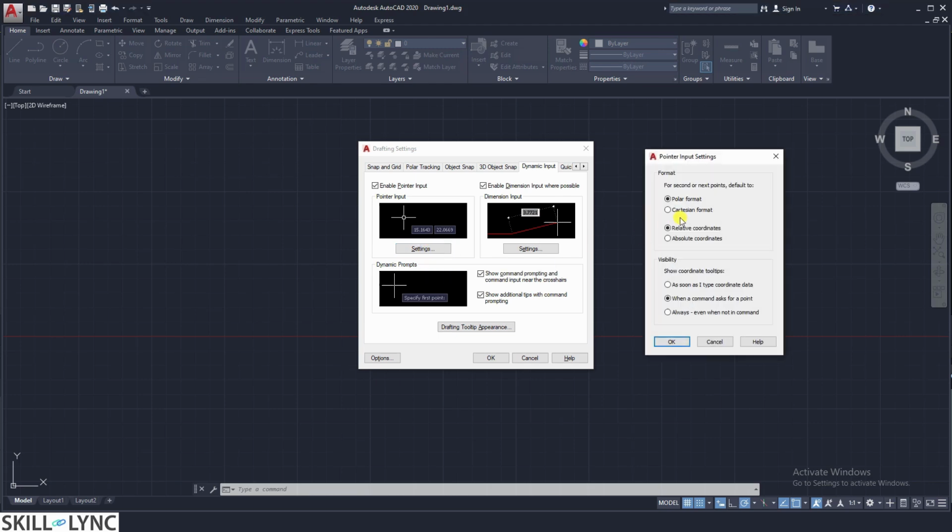In this setting, you can see by default it is referring to the polar format as well as the relative coordinate system. So when typing, we can change to the next value. So polar coordinate, as you could recollect from the week 1 session, when you are specifying a less than angle, it is selecting this. So by pressing on the comma, you can change from the polar to the Cartesian format. So when we are pressing on to the angle system from the Cartesian format, it will switch back to the polar. So let us do this once.